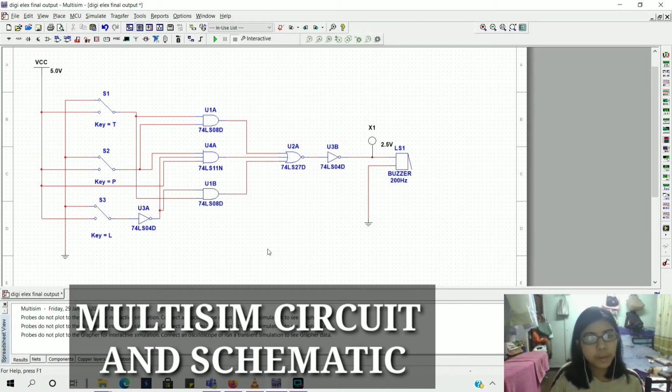This is the circuit for our experiment. As we can see, there are three inputs, which are the temperature, pressure, and fluid level. According to the principles in physics, pressure is directly proportional to the weight. Therefore, we decided that there are only three inputs for this experiment. The temperature is connected to the two AND gates, while the fluid level is connected to the NOT gate, and the output of the NOT gate is connected to one of the AND gates, and it is also connected to one input of the triple AND gate.